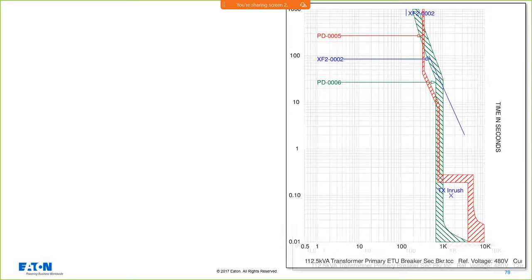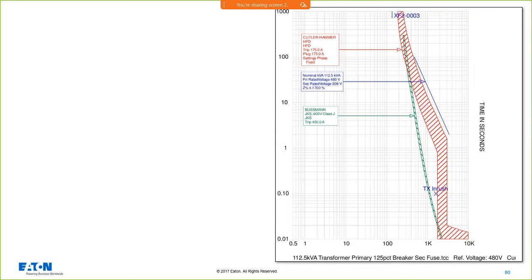So if I, for example, use an electronic trip unit on the primary and a thermomagnetic circuit breaker on the secondary, again, I don't have to worry about coordination. If I take out the secondary, if I take out the primary, it doesn't matter. It's just nice to have that overcurrent device. I could increase the long time pickup and make these align, but providing good protection of that transformer is an important part of that pie.